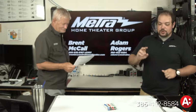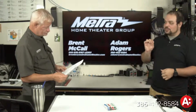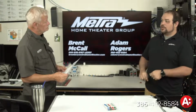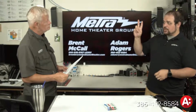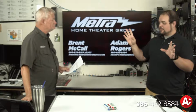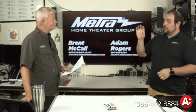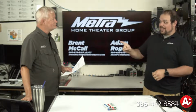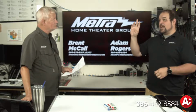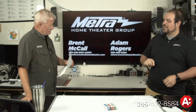So what you see here for Alternative A, the way that this works is interesting. It transports the power on the same conductors as the 10/100 data. So when we look at 10/100 data, we're using pins 1 and 2, because that's going to be either the green or the orange, depending on which one you subscribe to. It should be orange, pin 1 and pin 2, and then pins 1, 2, 3, 4, 5, and 6. Nope. Where am I at? Pins 1 and 2, 3, and we're jumping over from 4, 5, 6. 1, 2, 3, and 6. There we go.